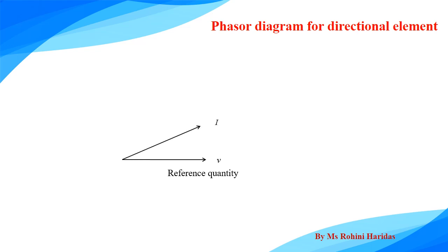The system current is generally lagging the voltage, but with suitable connection the relay current is made to lead the voltage by an angle of theta, and therefore in the figure current I is shown leading the voltage by the angle of theta. Here phi V is the flux due to the voltage coil and it lags behind the voltage by an angle of phi.